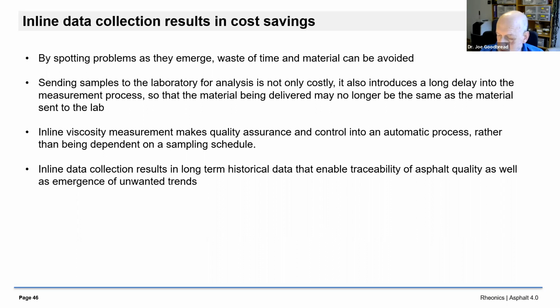In the unlikely case that it reports back that the sensor needs cleaning, it will alert the operator, and then you can pull it out of the system, wipe it with a rag soaked in solvent, put it back in, and you're good to go.